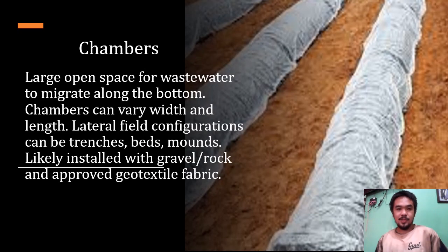We also have chambers. It is a large open space for wastewater to migrate along the bottom. Chambers can vary in width and length. Lateral field configurations can be trenches, beds, or mounds, likely installed with gravel and rock and approved geotextile fabric.